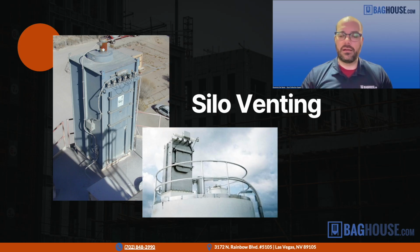Where they are used differently many times, though, is whereas a baghouse usually is pulling air from something with its own fan, bin vents are usually placed on top of something where you're pushing air or pushing material into. So the most common place is on top of a silo, or sometimes weigh bins or very large day bins. The reason we put them there is because as you blow air in with dust, it displaces the air that's already in the silo, and it needs to be vented out.